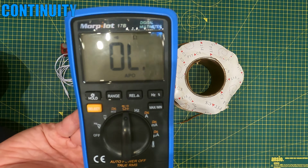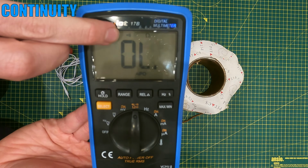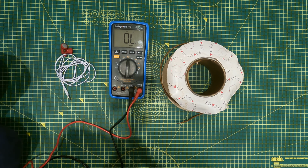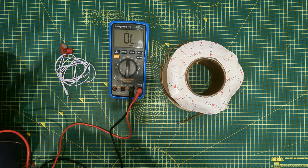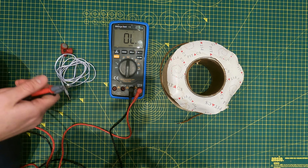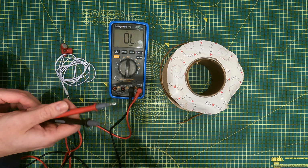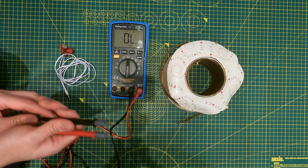Okay, so the next feature we're going to be looking at today is the continuity symbol, which is just there. So the way in which continuity works is you basically inject a small current down the circuit, and if it's complete you'll get an audible tone. If it's not complete you won't get an audible tone, which means there's a break somewhere in the circuit.